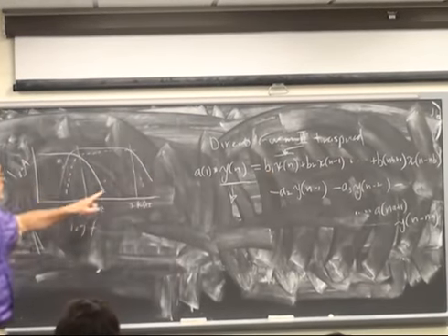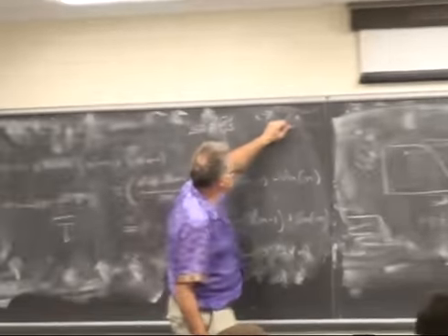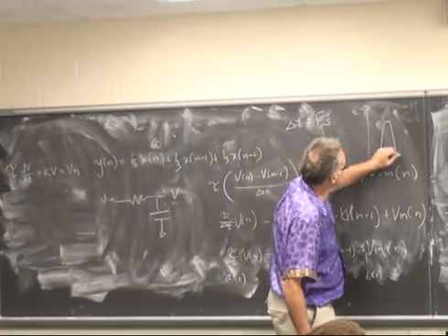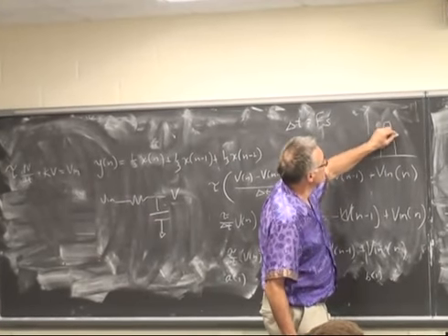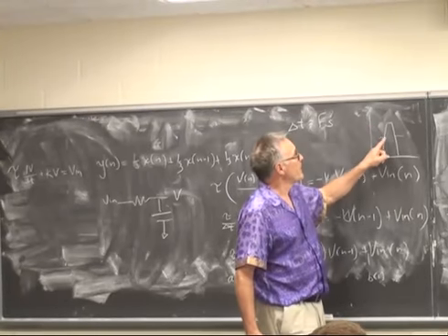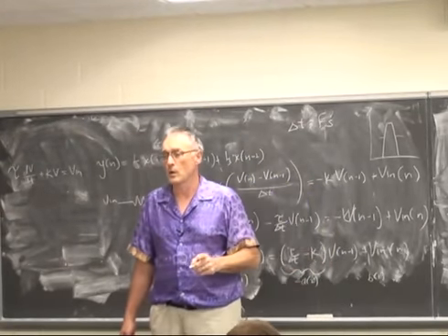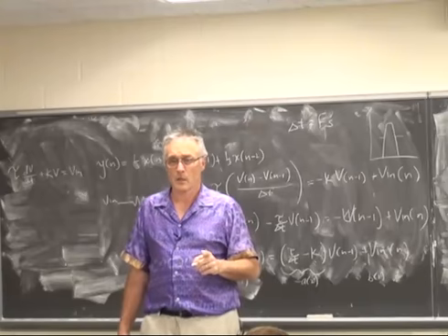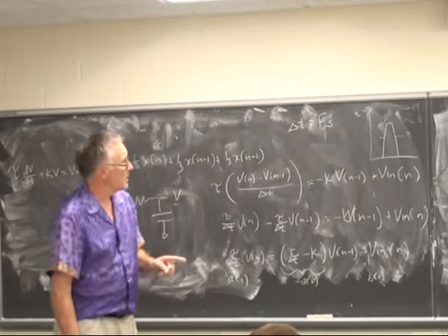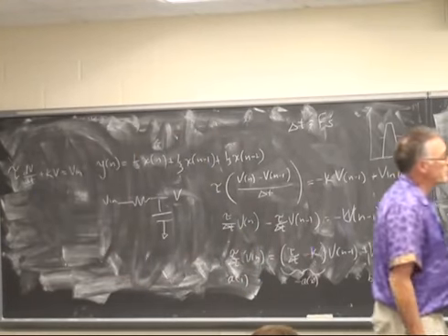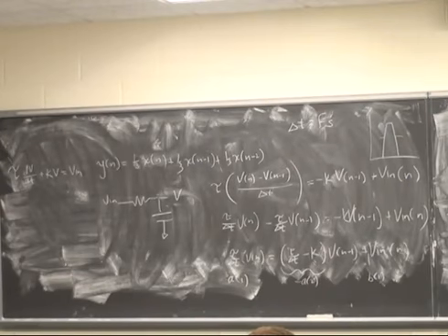If you ask for a filter that has a narrow bandwidth, then at least one of the coefficients is going to get very small. And when that happens, you're going to find that with a fixed point calculation, you're going to run out of bits.